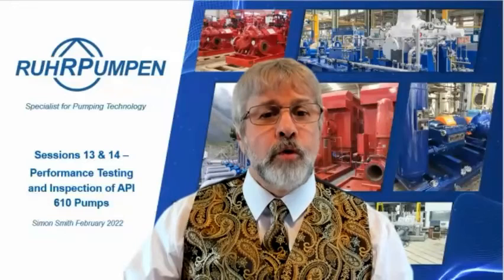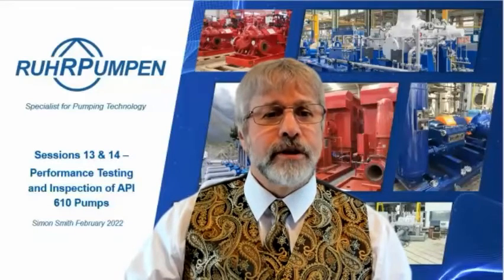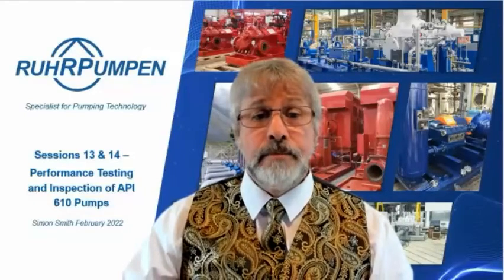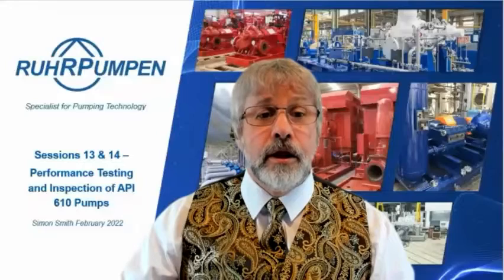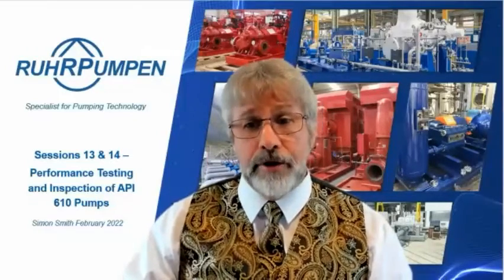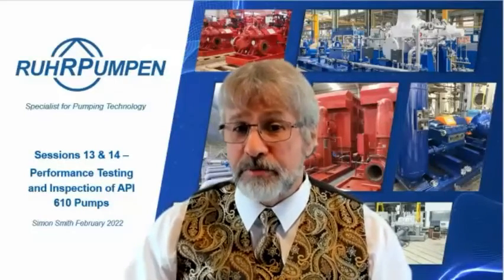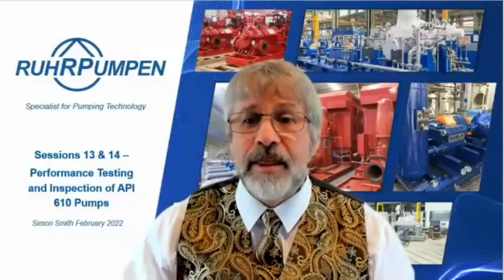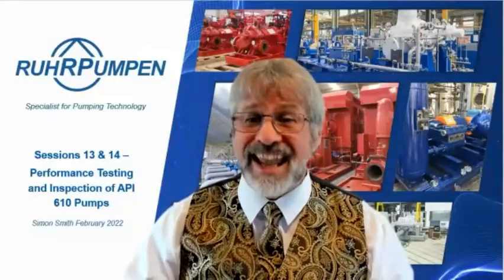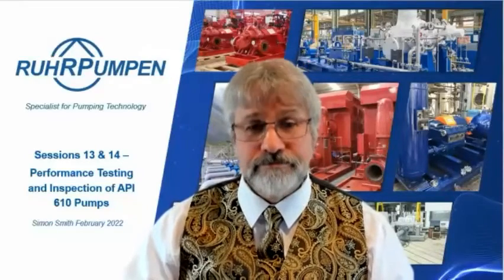Shyam Kumar, what will be the test duration of the mechanical run test, 1 to 4 hours, for oil temperature stabilization plus 4-hour running? Oil temperature stabilization can take up to 4 hours. It depends on the size of the pump. A small pump, it might be sooner. A large pump, it might take longer. Could be up to 4 hours. So therefore, that will make it an 8-hour test if you want a 4-hour run test after oil stabilization.